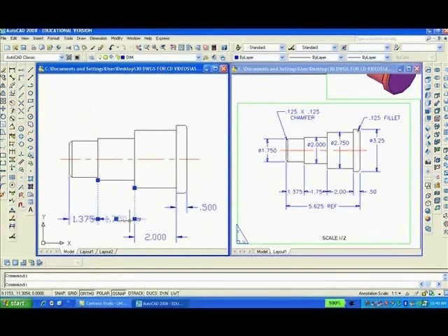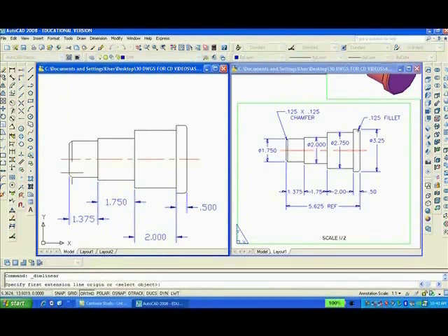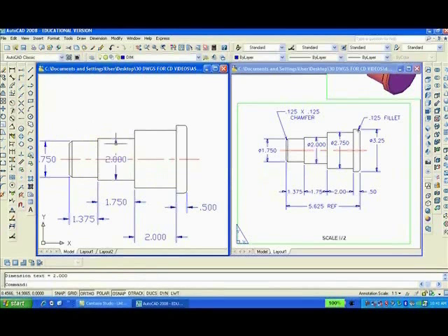This one doesn't look too good, so I'm going to change it. I'm going to take off the object snap. I'm just going to move it back a little bit, like that. It's always good to stagger dimensions anyway. Next, we'll go to a linear dimension with the snap on from here to here. Then we'll go from, let us say, midpoint to midpoint here.